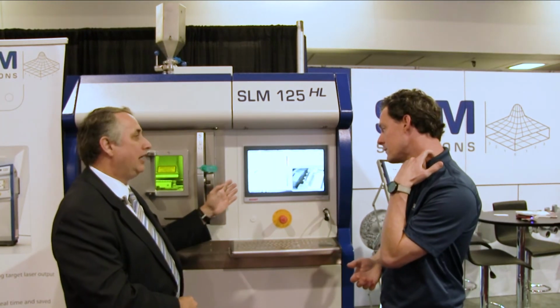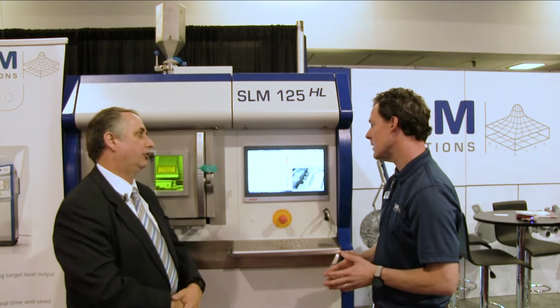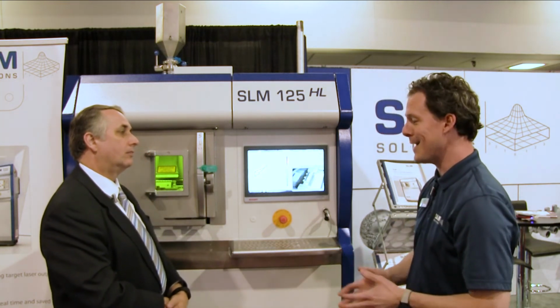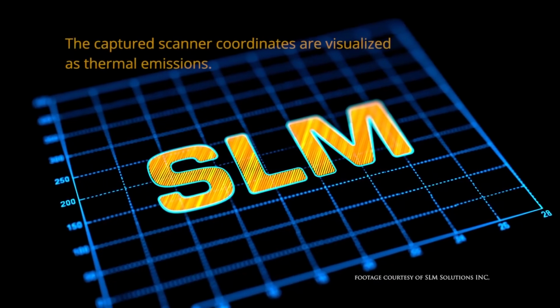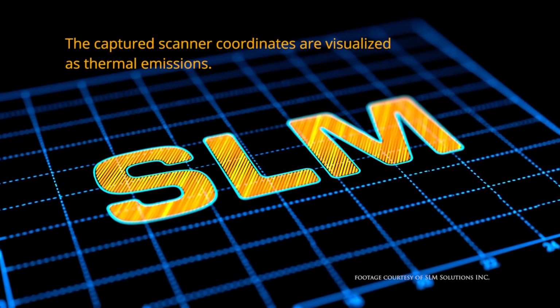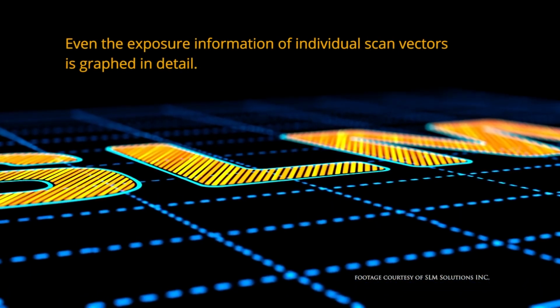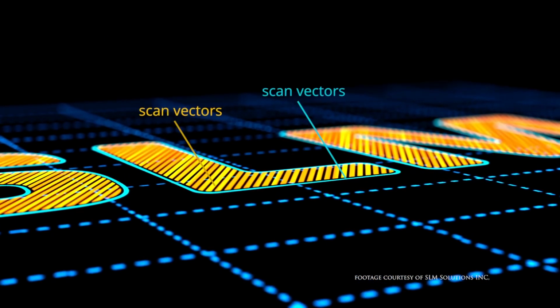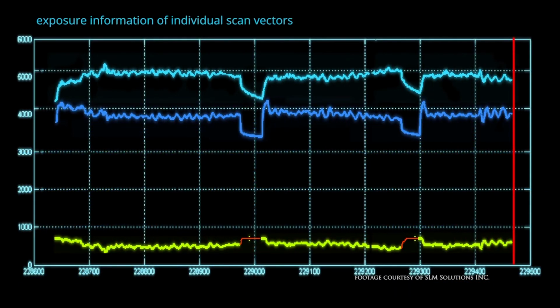Could this be considered a training aid? Is something you could use to actually bring people up to speed on how to design and run SLM parts? It is. I actually haven't thought of that myself, but yeah, you could, especially as it relates to the laser output. It would give folks again real-time insight into what's going on with the actual laser to understand if you are seeing any deviations in the thermal energy that's actually hitting the powder bed,